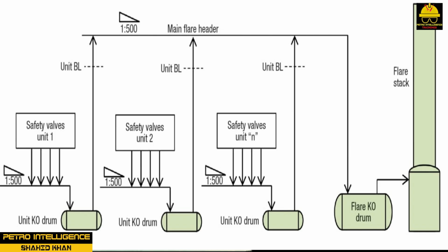overpressure situations. Many units that process volatile hydrocarbons have two collecting systems, a warm-wet system and a cold-dry system. This separation is made to avoid freezing, with consequent plugging due to ice formation of the wet vapors. Both systems go to their respective knockout drums, where the cold vapors are warmed and then combined and sent to the flare stack.